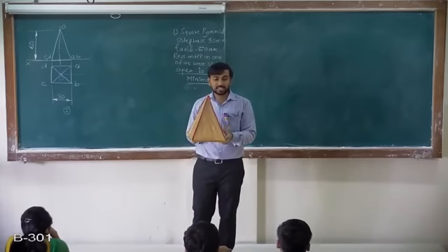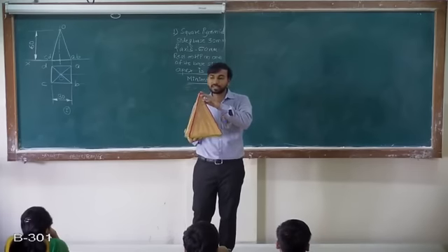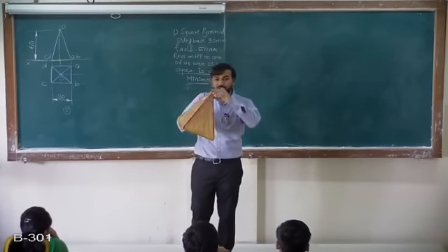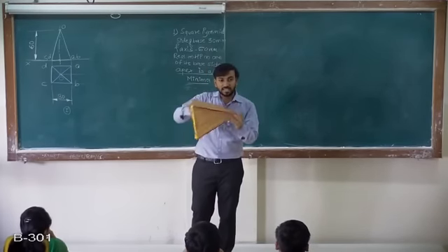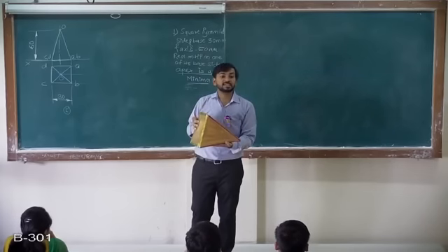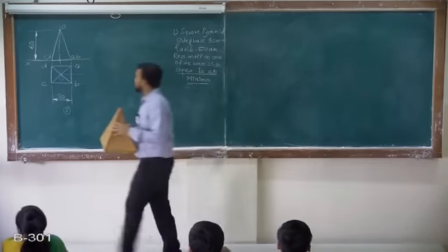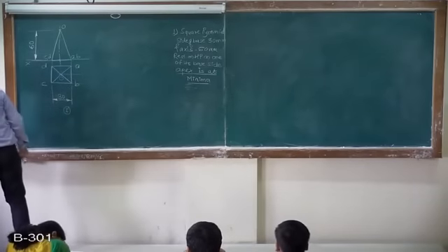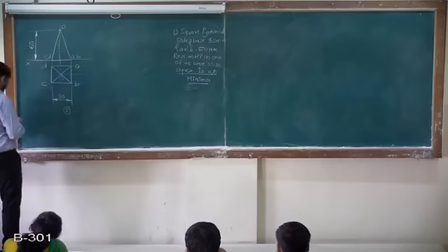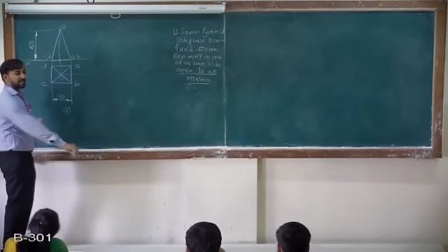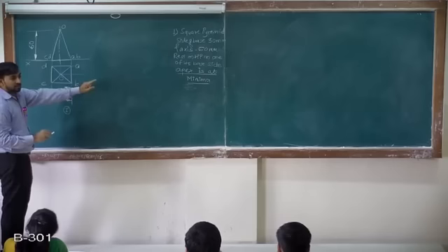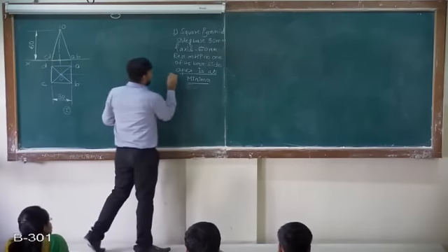First condition is this. Second, the apex is at minima, so its minimum position when it is inclined should be on XY since it is on HP, right? So I will draw the second condition. Apex is at minima, that means it is resting on this, the second condition.